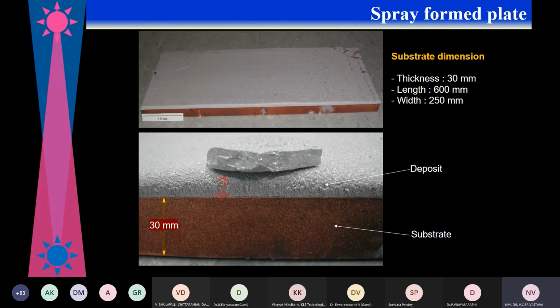With this composition, if we use powder milling, ball milling, mechanical alloying, or rapid solidification, then we can get 100% amorphous material. But by spray forming up to 12 millimeter, we could get different fractions at different distances. At the bottom, we could get around 90% amorphous material, but as we go to the top, it reaches 60% amorphous. But why is it possible?